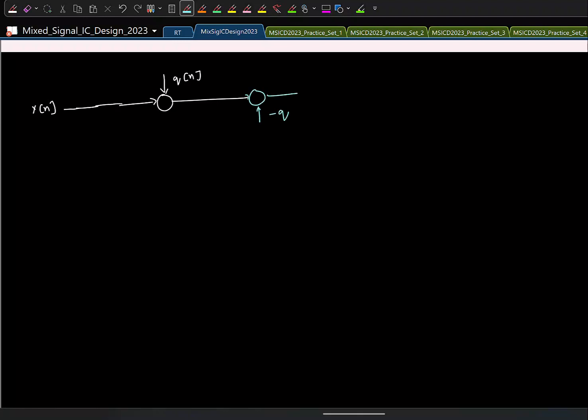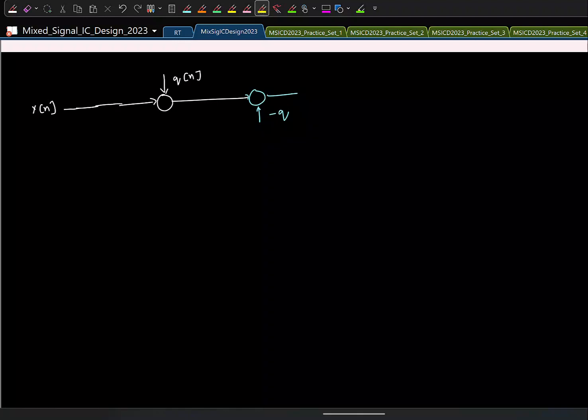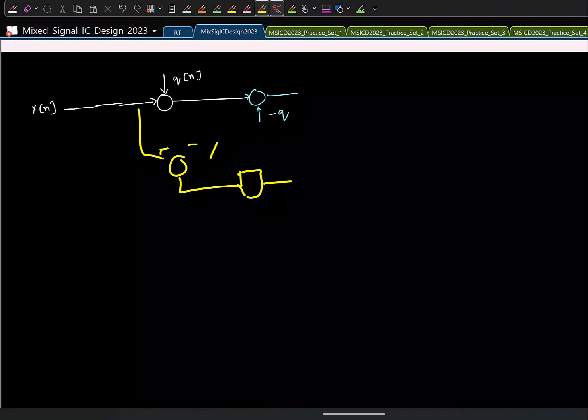This is what the basic principles are, right? And of course, to get Q of n, you have to subtract this guy and this guy, right? This guy is digital, this is analog. So what did we do? Yeah, we put a DAC. So we put a DAC here and then took the difference at another ADC and did all this. That's what gave rise to pipeline.